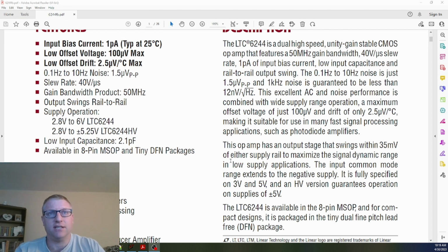So whatever you have on N plus, you should have on N minus. But of course, because of the input bias current, you always end up with some sort of offset voltage, and this can be handled or mediated in a multitude of ways.